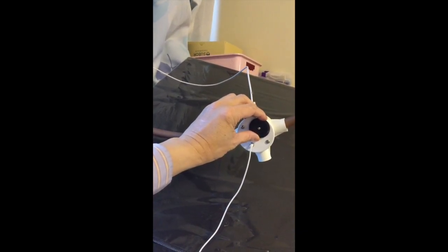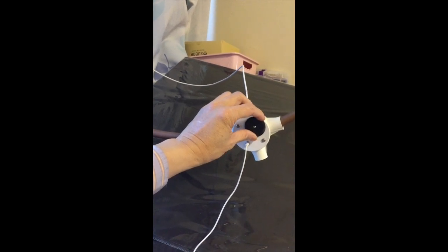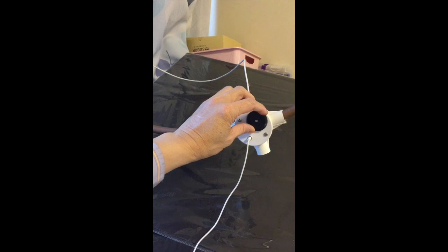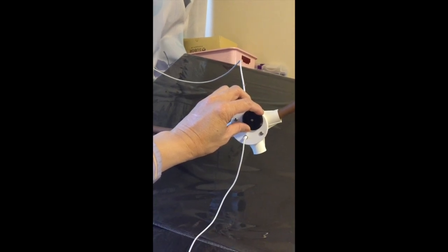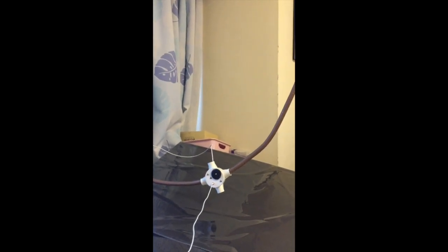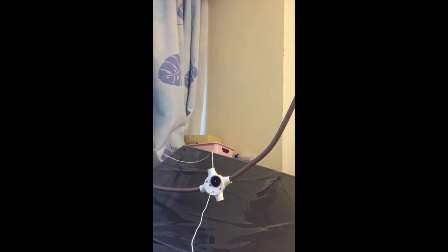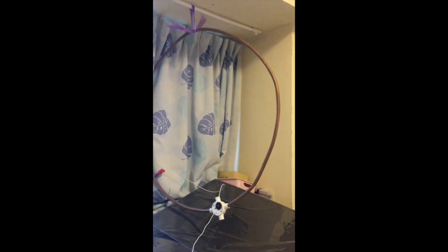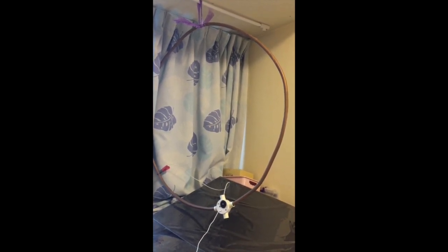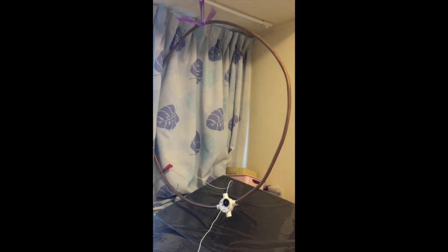This is because different paths are used to transfer the shortwave to your radio. It may travel through different paths, and when they collide or combine together, the different phases may cancel out some of the radio wave frequencies. That's why you hear suddenly it is loud, suddenly it is soft, and you just need to try your luck and keep listening and searching for more stations.